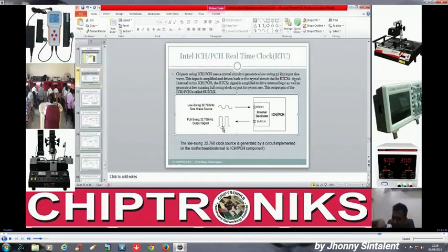Everything in the notebook motherboard, if you are talking about power consideration, the turning on of the notebook motherboard, everything starts from ICH or PCH and ends at ICH and PCH. RTC, PLT reset. This is the start and end of the power sequence. Mind it, power sequence only. Everything starts from ICH or PCH.